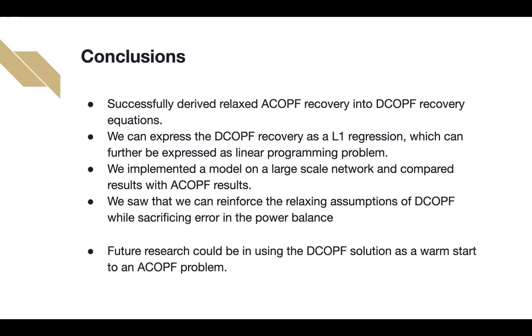We need more slack. For future research, it'd be interesting to see if these solutions from the DCOPF recovery are good enough to be used as a warm start to an ACOPF recovery problem. If we're doing some sort of sensitivity analysis, running a lot of optimal power flow problems, we want high resolution.